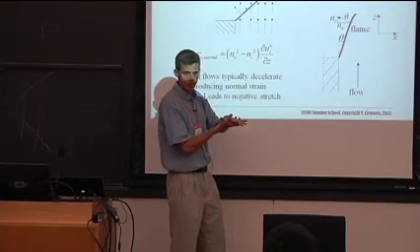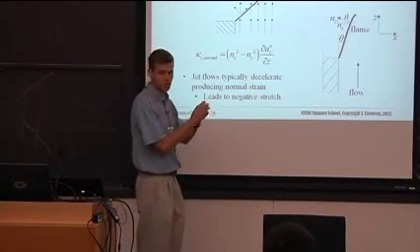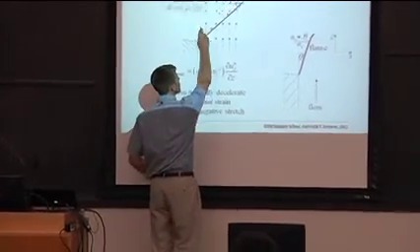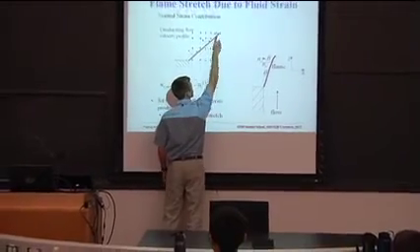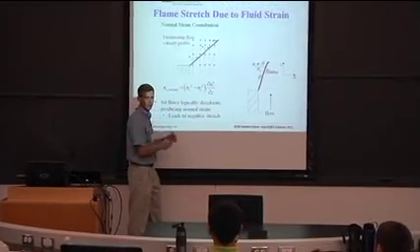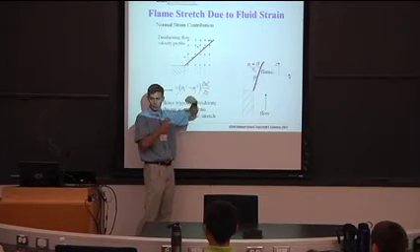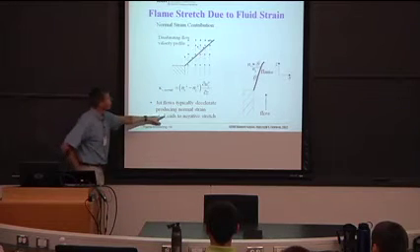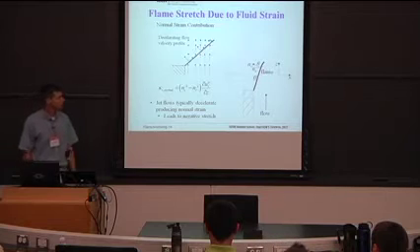The Lagrangian fluid mechanic volumes are changing their shape. So what's that doing to the flame? Again, let's decompose it into the normal and tangential components. And look what's happening to this tangential component as I move along the flame. It's decreasing. So what's that doing? The flame is getting compressed. That's negative stretch. So what you can see is fluid mechanic deceleration leads to negative stretch.